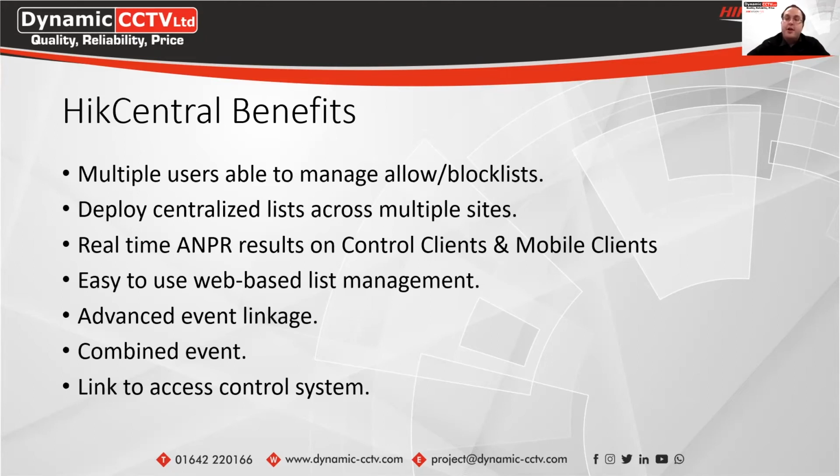If it's being used on a large system and you have lots of remote sites added into HikCentral, you can actually apply those plate lists across multiple sites. And I have actually tested our ANPR camera with 10 separate lists linked through HikCentral for the actual linkage actions and for the alarm events on there. So it does give you that kind of flexibility within the system.